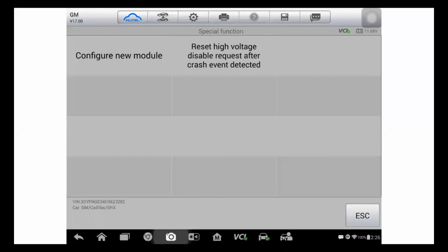So we went in and took a closer look at the connectors and found some spread pins. So what we did was we rewired the connector in the driver's door, left door, and we rewired the connector at the left front, the one above the RAV saddle. After we got it done, we went in and tried to run the configure to module routine on the scan tool.